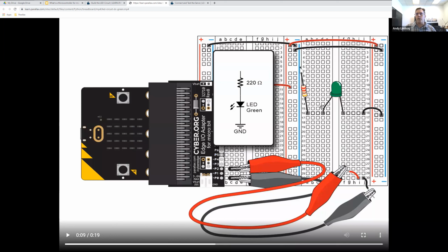peanut-shaped parts with the 4 color bands are resistors, and they resist the flow of current. And notice that we're putting one end in, and the other end is connected to the light emitting diode, and the other end is floated, and we can see that, hey, look, it's in the same row. So yes, they are electrically connected. Then the second to last step is connecting the other end of that resistor to the 3 volt bus strip. And then we see the 3.3 volt schematic symbol there.